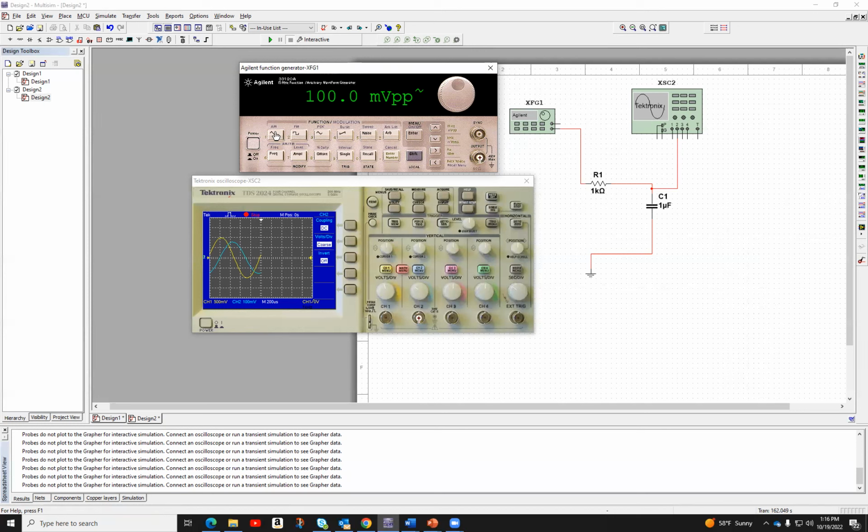And what I want to do is change the amplitude and the frequency that I want, right? So I'm going to select, you can see here the button, the second one from the left says amplitude. So I'm going to select amplitude, and there are 2 ways I can select the amplitude. I can use this big knob and start changing it, and this will give you a little more precision, but it's hard to go to the point that you want that way. Another way that I can do this is I select the digit by using these buttons here.